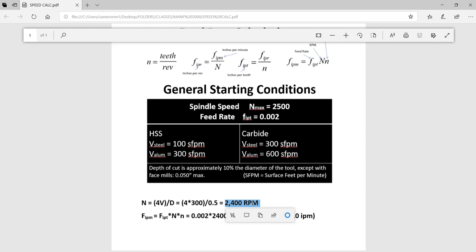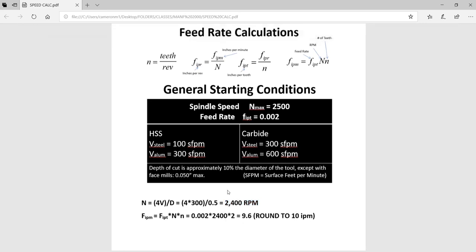Now, in the lab, we're used to cutting closer to 1600 to 1800. We do that in CAD/CAM and in 1000 for safety. If a part gets chucked out of a lathe, it's a lot safer to have it do that when the spindle's spinning a little bit slower. So that's the reason why we have a discrepancy here.